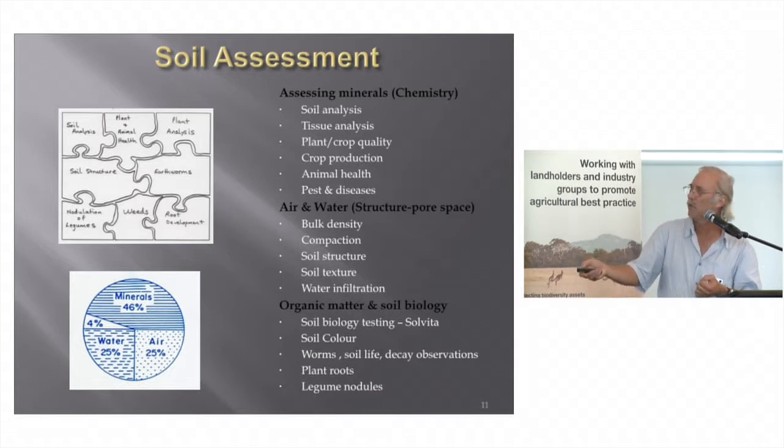Air and water, how can we learn from air and water? It's not necessarily a part of every soil analysis you get done, but you can ask for bulk density, which gives you a little bit of an idea about maybe structure of the soil and pore space. We do digging in the soil, which many of us have done, to have a look at compaction. If I use a highly technical piece of equipment imported from overseas, it's actually a bit of fencing wire, just probing into the soil to get an idea of compaction. Now, it doesn't take too much skill to actually recognise when there's sufficient moisture in the soil, if there's compaction issues in your soil. Digging in it, putting water in the top part of the soil, see how quickly it infiltrates will tell you about the soil structure itself, and pore space, air and water.